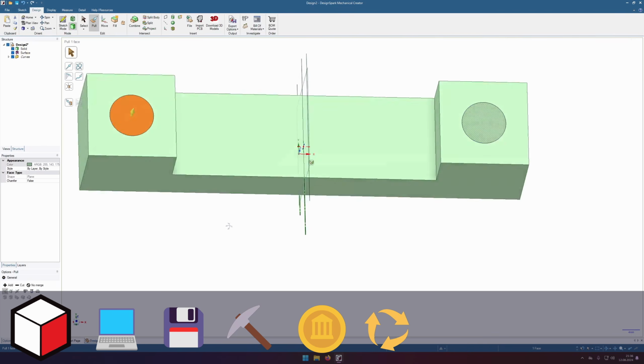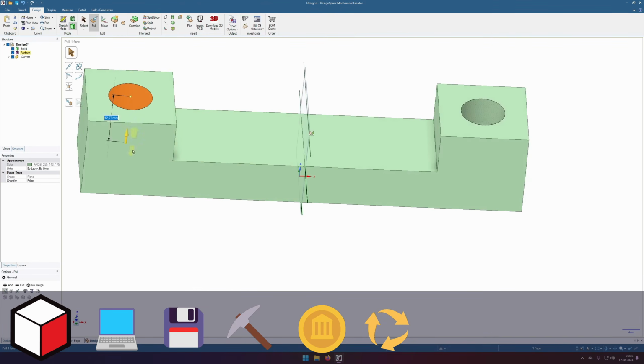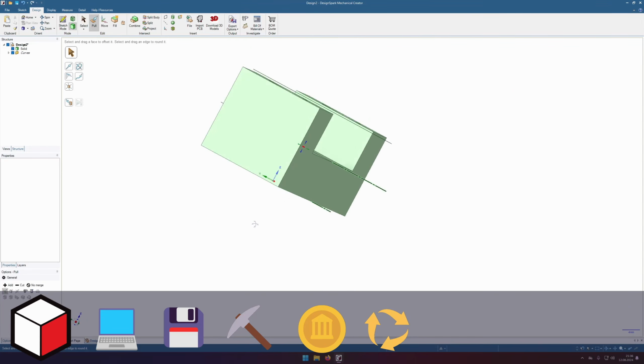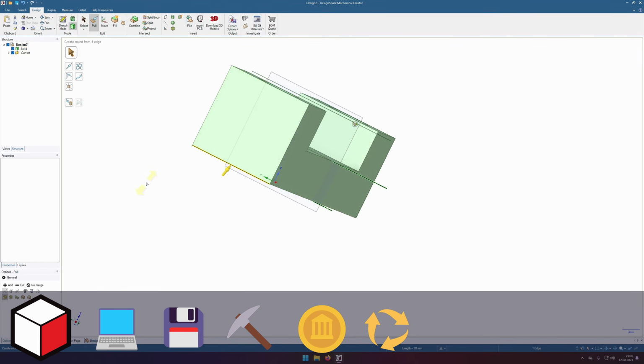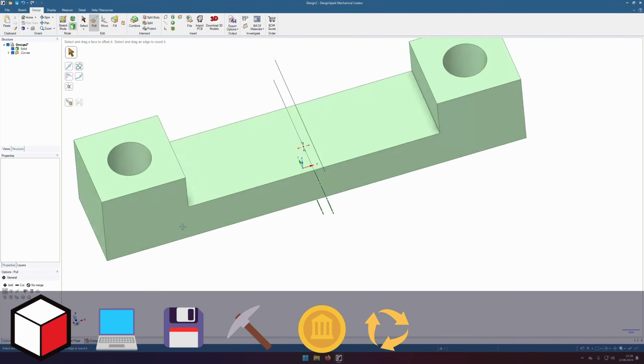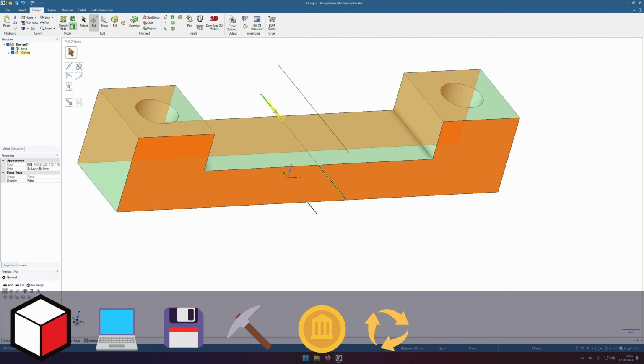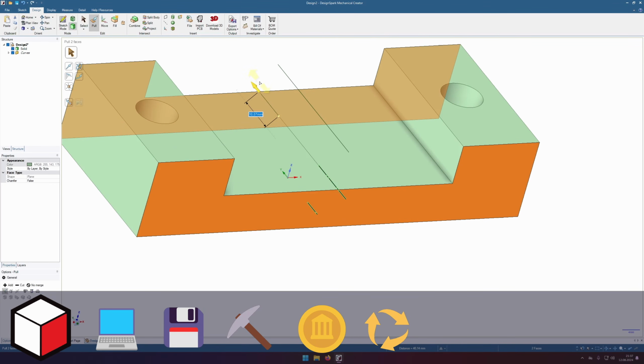While step files can be modified by any CAD software, if you would like to modify a hole, in case of FreeCAD, you will need to sketch a hole, and you will need to do it for every single feature you want to modify. But with DSM and direct modeling techniques, you can do that much faster. It also converts STL files nicely to step, and you can modify them as well.